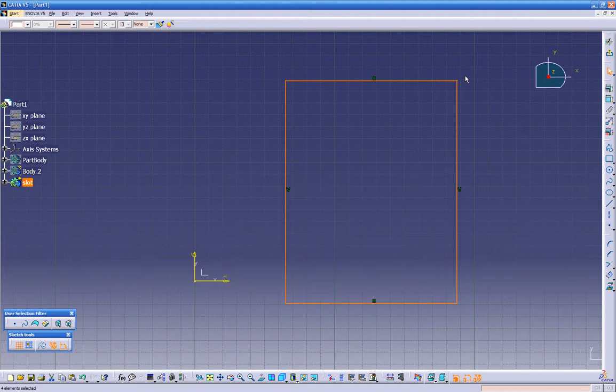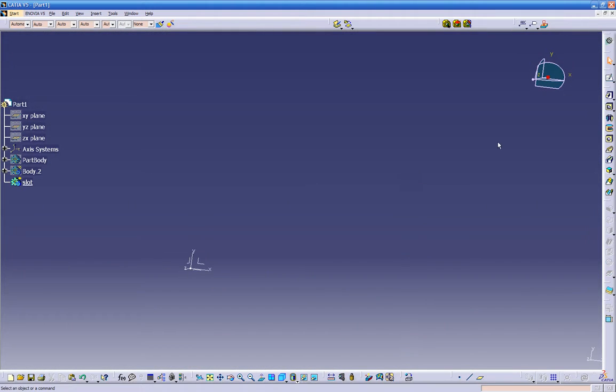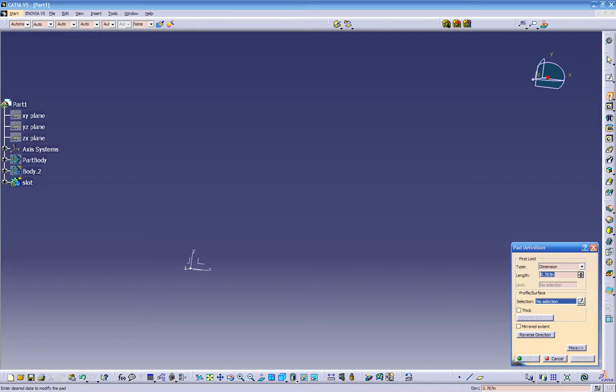Before I do this, I want to show something else. We can create a rectangle without doing the sketch first. We can do it from the pad icon. So let's cancel that, get out of here. Instead of going here, coming over here, creating a rectangle, and opening a sketch, there's a couple steps, but what we can do is just click straight on the pad, and if you look down here on the selection, it's got the sketch button.